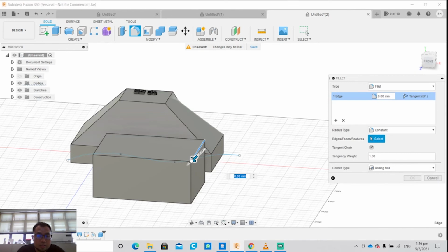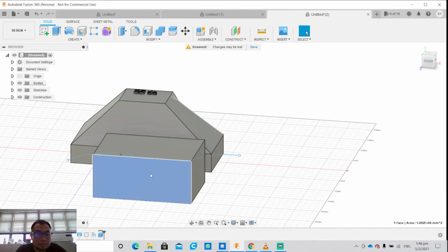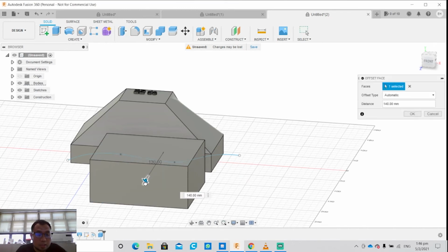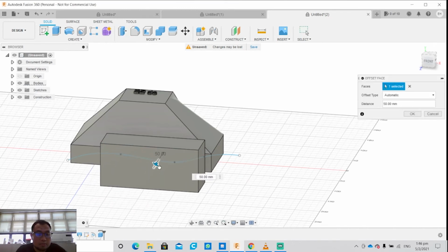It all depends on what type of handles you are selecting. If you are selecting a face and you press pull, it actually grows, extruding the face and all.